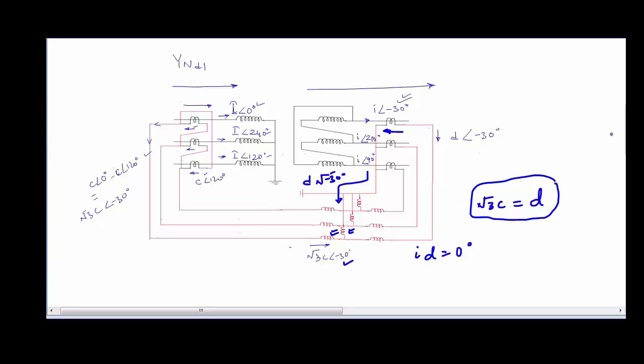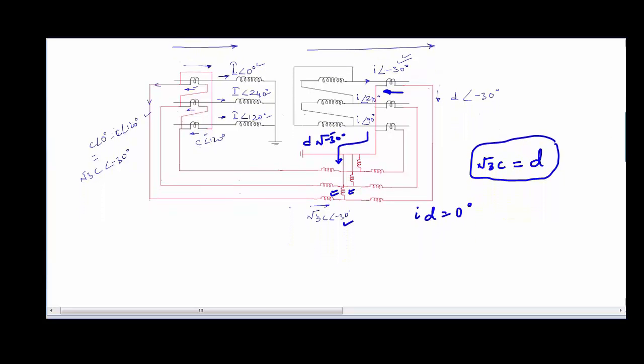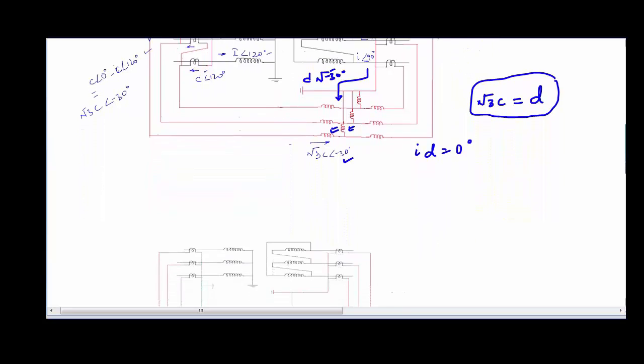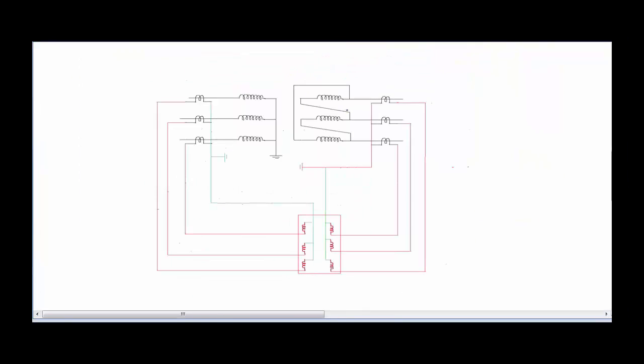But how is the relay going to behave when there is an internal fault in the transformer? Well, in order to see that, let us take our discussion to numerical relays because it is easy to understand. So talking about differential protection of three-phase transformers with the help of numerical relays, this is how the circuit will look like, and this one represents the numerical differential relay, which I am marking as 87.